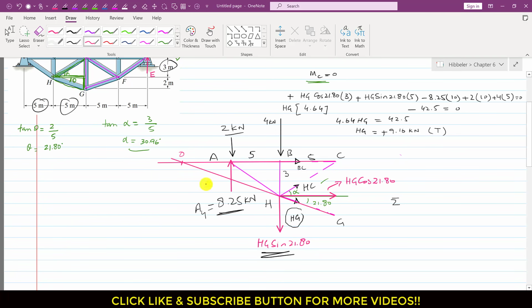So now if we apply the summation of moment about this point O, since the line of action of both of these forces, BC and HG, are passing through that point O, they will not come into our equation, and we will have only this HC force as an unknown force in our equation, right? So now we have to apply the summation of the moment about point O equals to 0. But before that, we need to find this OA distance, right?